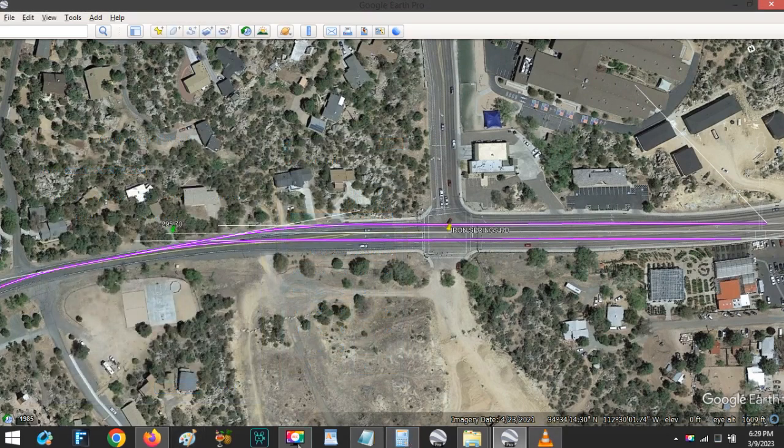But the problem is, if you move that point of vertical intersection back from the station, you're going to get a steeper grade, and you don't want that. So I think it might be best to leave this vertical intersection in the center of the station, and perhaps have it a little bit higher with a very long radius of vertical curve.